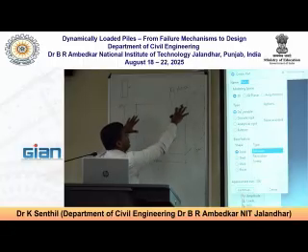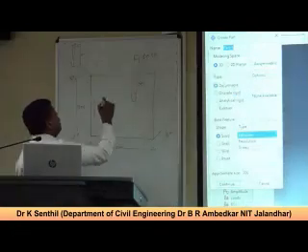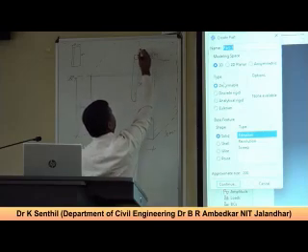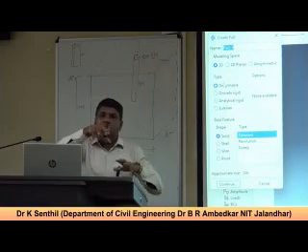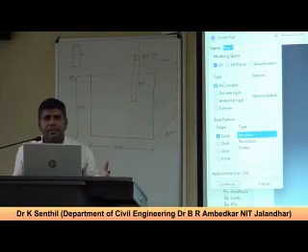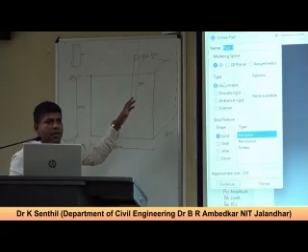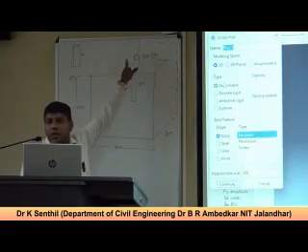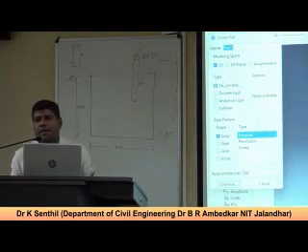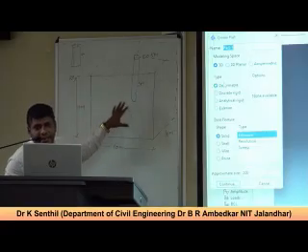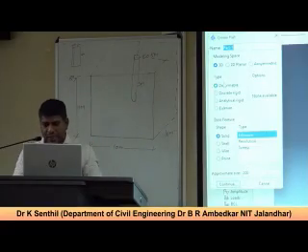So now this is one approach. Also, you look at this planar, the whole model. You take a quarter model, maybe like this, and this portion. You model this quarter model so that the computational cost may be reduced. Because if this model takes 1 hour to run, if you model only the quarter portion, you may get your results within 15 minutes. So you can do it in different ways. Now, okay, let's try the 3D model and consider this.